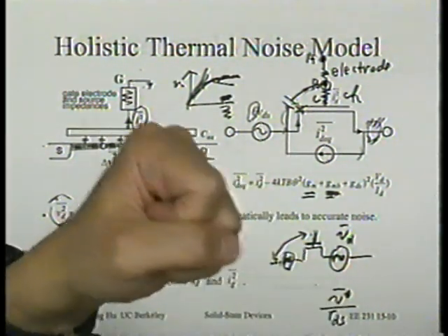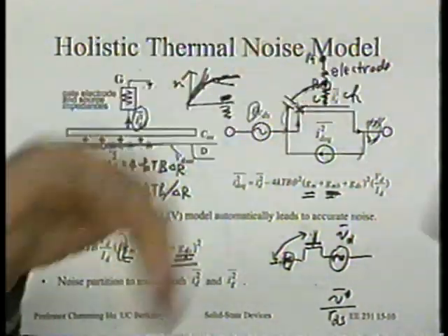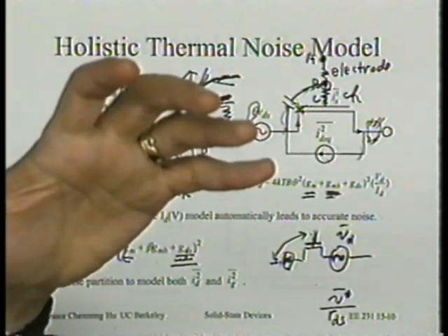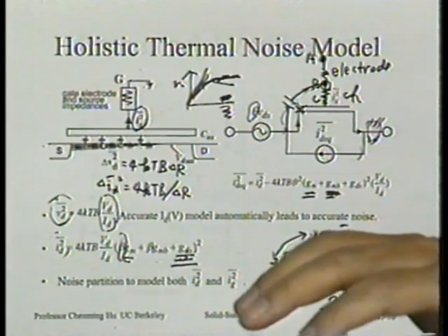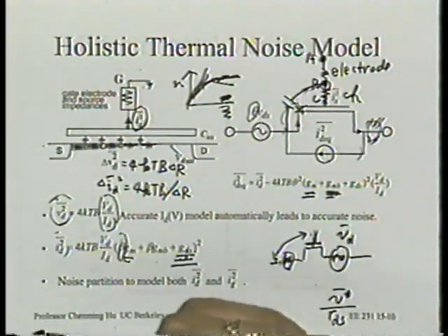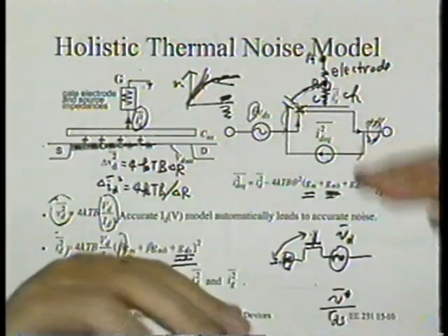So these two antennas, if they're coherent, give you a power of 4. If they're incoherent, just two separate antennas, each gives you a power of 1. You only get a power of 2. You see that? Same thing with the noise. So it's very important to be able to figure out whether they're coherent or not coherent. How do you model their coherence? Yes, question. But if they're coherent, and they're opposite signs, then you have 0 power. Exactly. So you also have to figure out what they are.